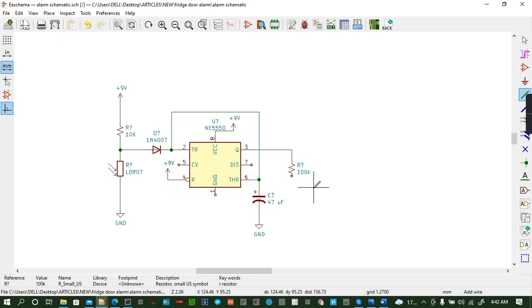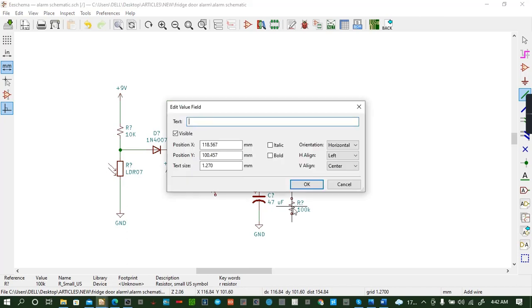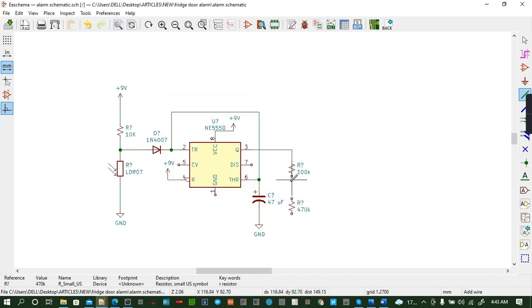Then it is interconnected to another capacitor of 470. So you can copy this one again and paste. Then the value, which is now 470k. Like that. You can place it as OK. Then you can interconnect it from here to this point. From this point, it goes this way. Then from 3 like that. We are good to go. So far so good. Very nicely.